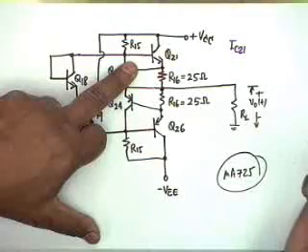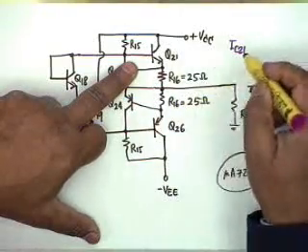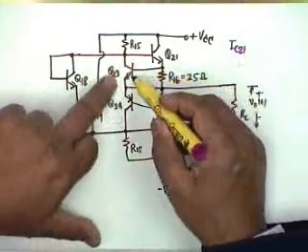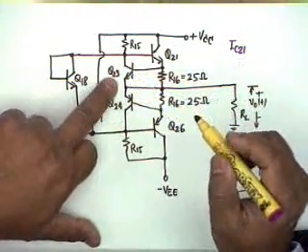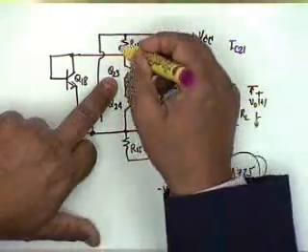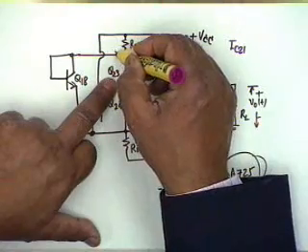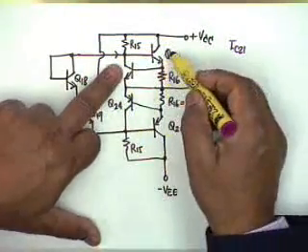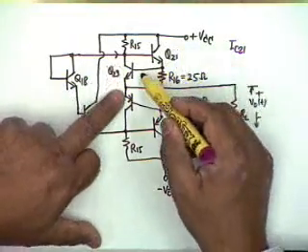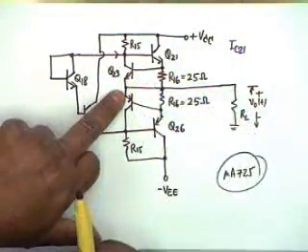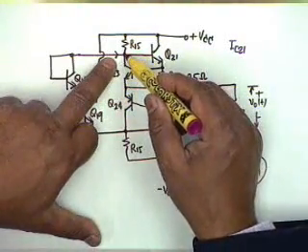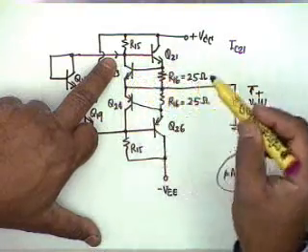But as soon as IC21 is large enough to make the transistor Q23 be on the verge of conduction, then the input current does not totally go to Q21, right. When Q23 starts conducting, the input current has to have two parts. One goes through IC23 and the other is IB21.